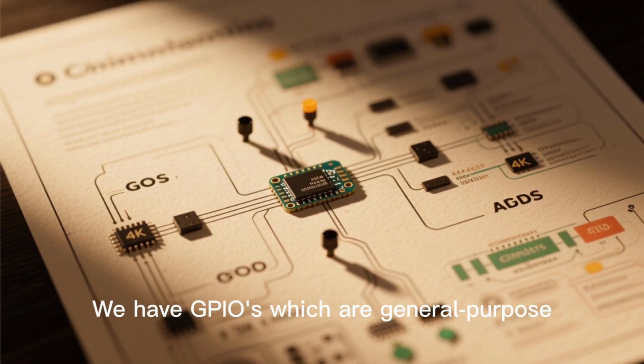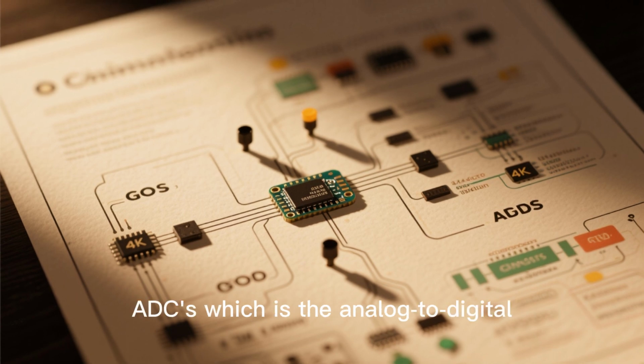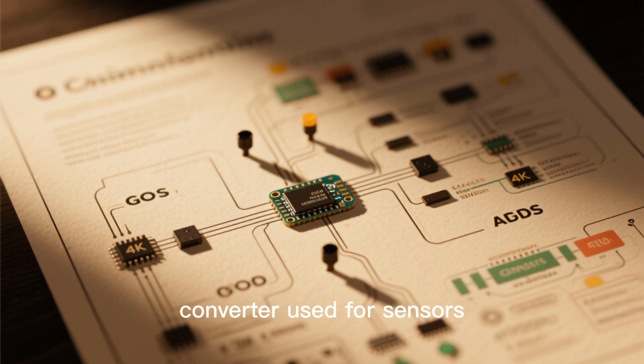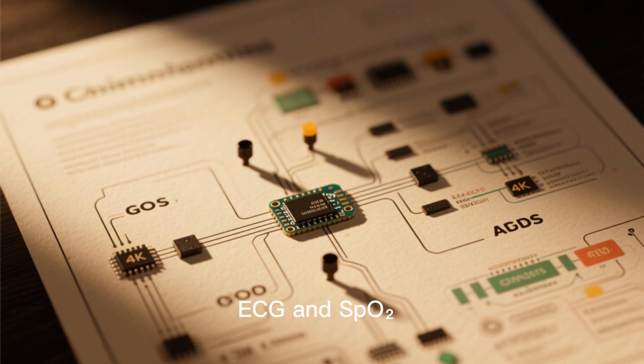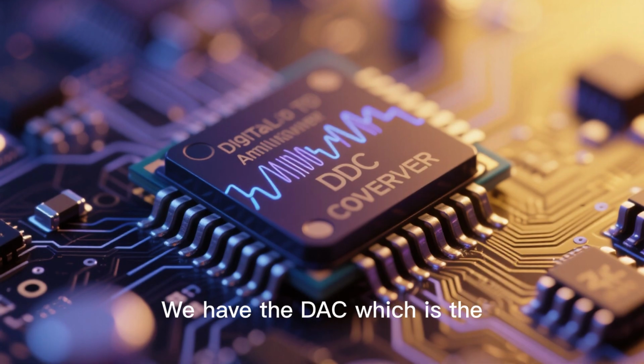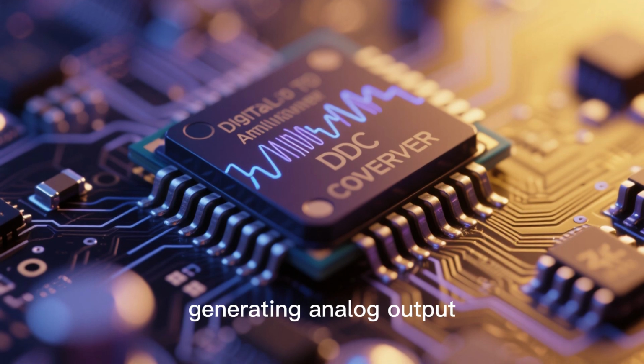Alright, next, let's quickly go through the pin functions. We have GPIOs, which are general-purpose input-output pins. ADCs, which is the analog-to-digital converter used for sensors like temperature, ECG, and SpO2. We have the DAC, which is the digital-to-analog converter used for generating analog output.